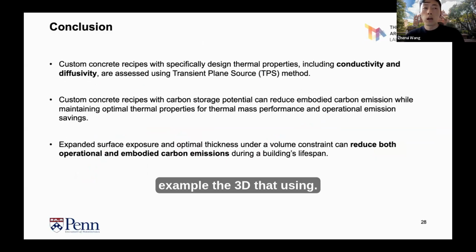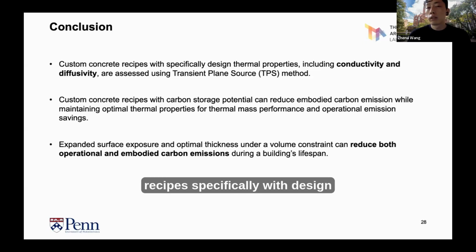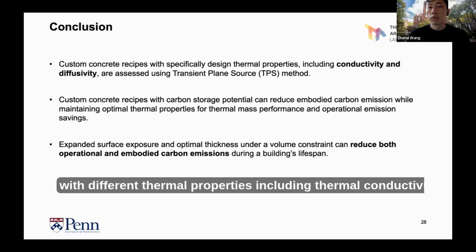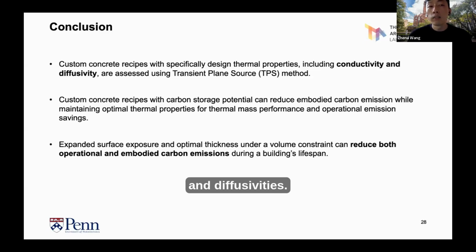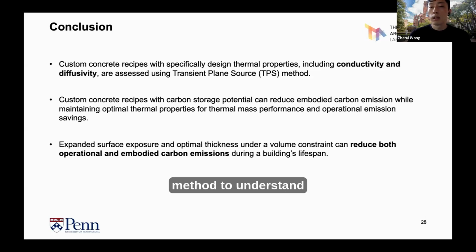So to conclude our work, we devised custom concrete recipes specifically designed with different thermal properties, including thermal conductivity and diffusivities. And we used the transient plane source TPS method to understand the material properties.